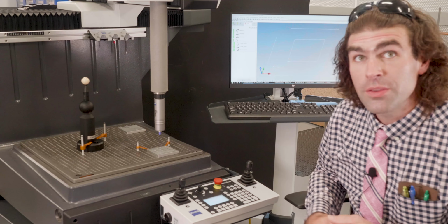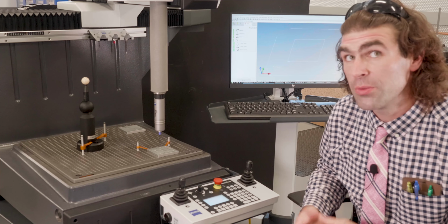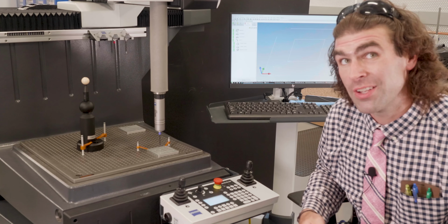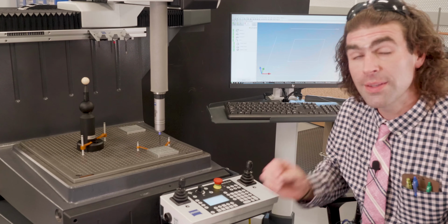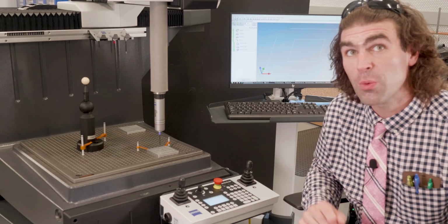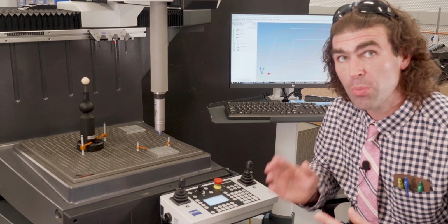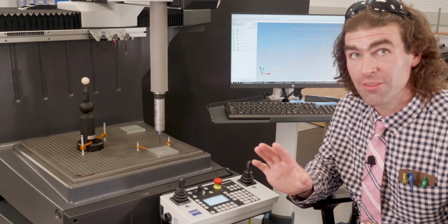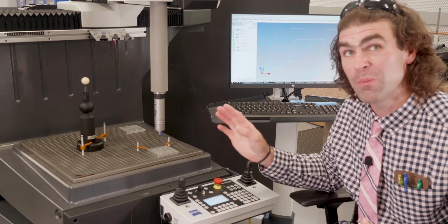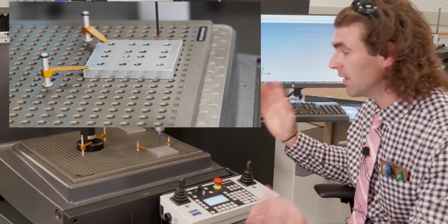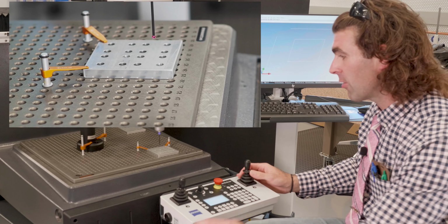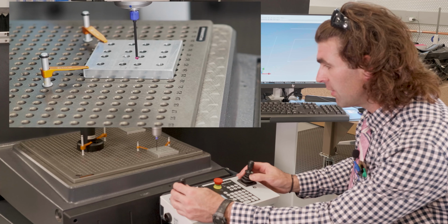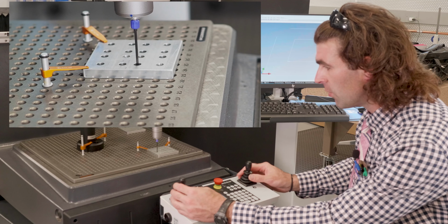Now, unfortunately, there's no way to really speed through this process. You've got to probe every single hole, okay? So you could go in and take the 4 points. Another way to do it is with something called a 4-point macro, which is great for situations like this where you have a bunch of repetitive holes to check. So the way the 4-point macro works is I'm going to drive into that second hole.